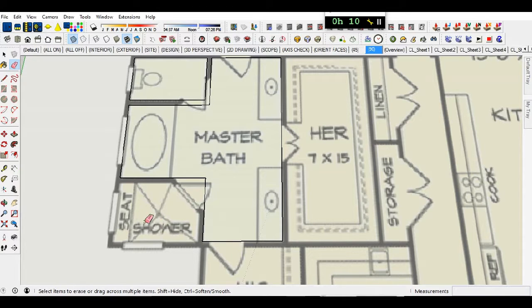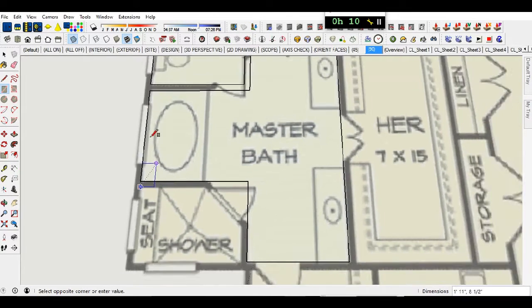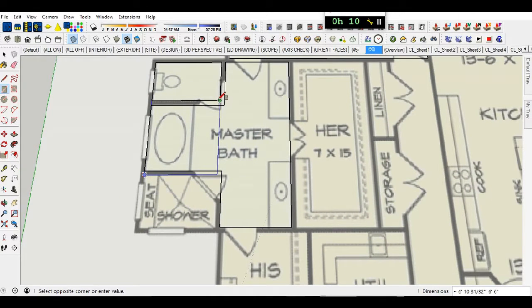Okay. And then the next guy, again, just keep referencing as often as you can. Once you've got two corners referenced, you can go ahead and hit that magenta shift button, and that will lock in those two references, and then you can grab your third reference like I did from this bottom corner here.